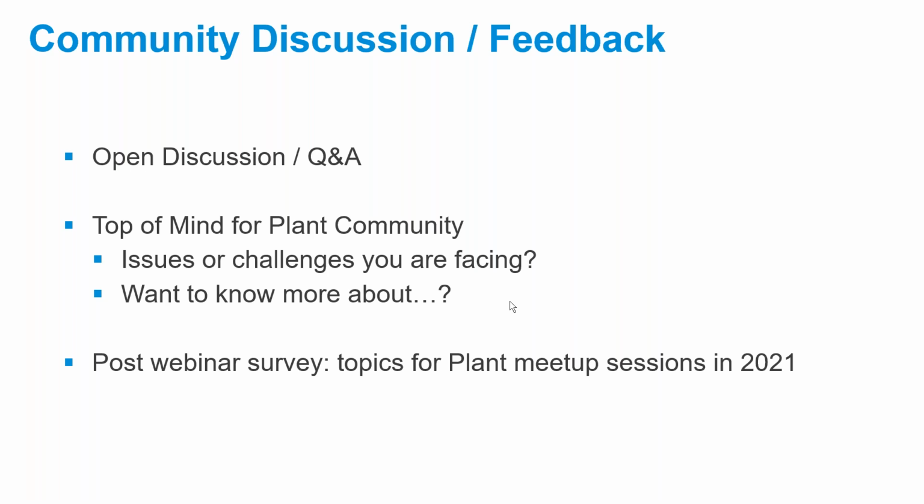So, Jason, did I cover too much there, or do you have anything to add? Oh no, I was just thinking the other thing that sometimes people aren't aware of is, if you search on Autodesk Knowledge Network for Navisworks coordination models. If you have the Civil 3D drawings and layouts in Navisworks, you can save it out to an NWD file and attach that into Plant without having to actually load it in. You're just putting sort of an overlay in there where you can see the Civil 3D surfaces and the models, but they're not actually part of your project, so they're not bogging it down.